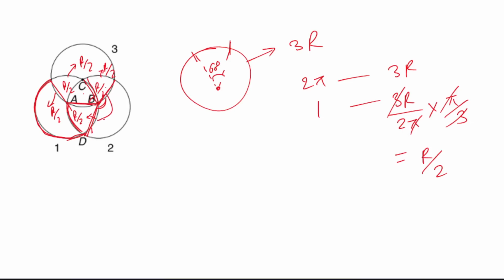So the rest is clearly 180. So this is actually half of this ring. This portion is going to make an angle of 180 degrees at the center. So its resistance will be half of the complete ring, that is, it will be 1.5 R.